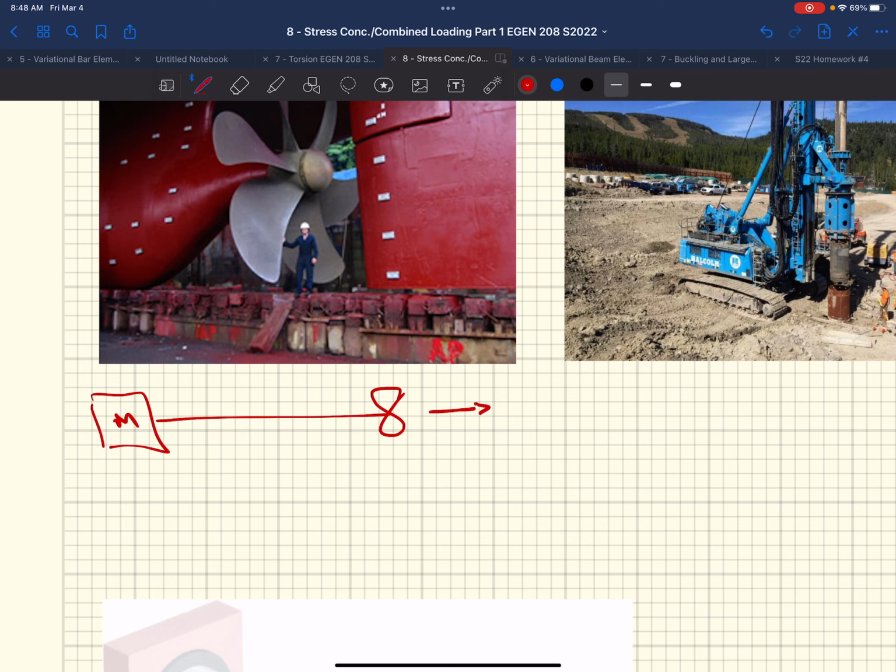we're going to want to push our boat to the left. Well, if the propeller is pushing our boat to the left, we're going to have to push on that propeller. The water is pushing back on this propeller and the propeller is pushing on the water, equal and opposite forces. And so we're going to end up with an axial force in this shaft. And then we're going to have some sort of pillow blocks, thrust blocks on that shaft, like we talked about. The shaft might have U-grooves in it that hold that shaft to the hull of the boat. That allows that axial force to get transmitted into the boat, and then we get a thrust forward.